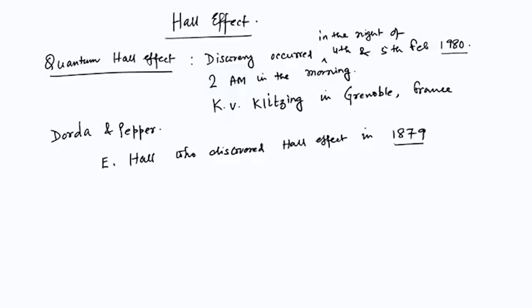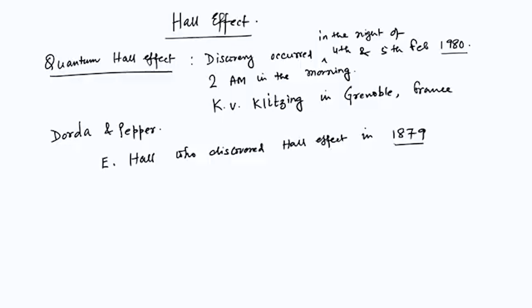I'll discuss that experiment that one does in the undergraduate labs of any of these institutions or any of the teaching colleges or other institutes that one has. And it was found that this experiment by Edwin Hall very accurately measures the type of semiconductors from the sign of what we call the Hall coefficient, and it also gives a nice order of estimate for the density of the carriers. So the Hall resistivity, I'll just give you an example of what Hall resistivity is,